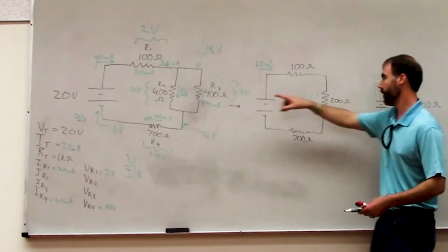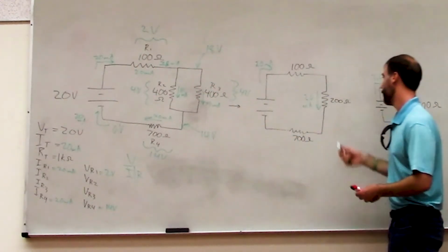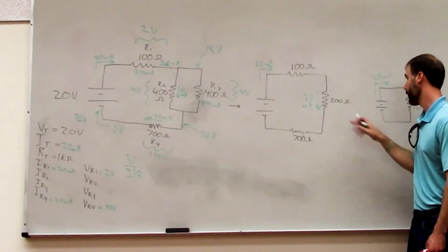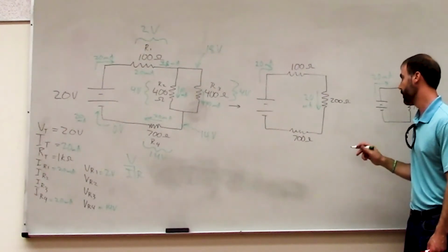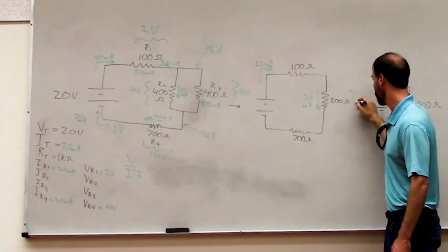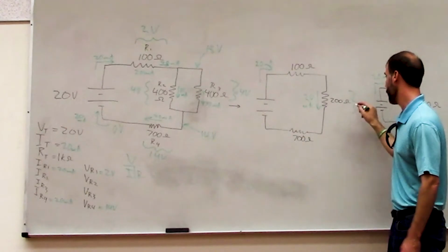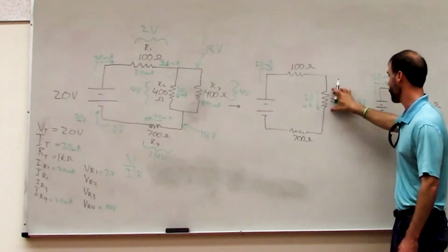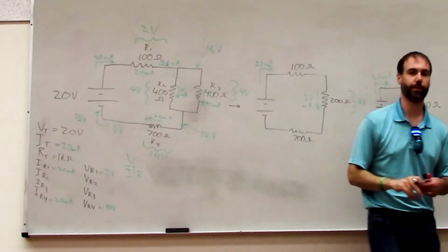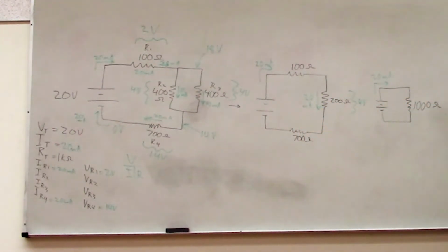This resistor is equivalent to those two. So you can say 20 milliamps times 200 ohms comes out to be 4 volts. That's Ohm's Law. So you could use Ohm's Law with this circuit. Say that there's 4 volts across this resistor, and that's equivalent to those, so there must be 4 volts across those resistors as well. So there's several different ways of doing this, all right?